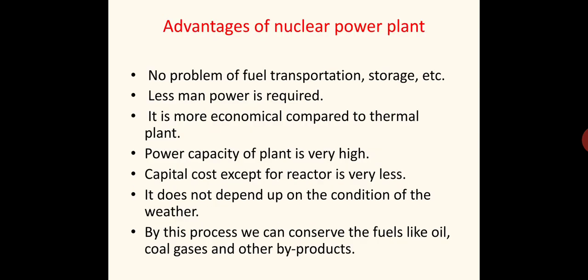Now coming to the advantages of a nuclear power plant. There is no problem of fuel transportation, storage, etc. That is the main advantage. Less manpower is required. It is more economical, with less manpower. Of course, very much technical knowledge is required for the person operating this. It is more economical compared to a thermal plant. The power capacity of the plant is very high. The capacity cost except for the reactor is very low. The cost of the reactor is actually very high, but the total cost is less. It does not depend on the condition of the weather. Whatever the weather, it will work. By this process, we can conserve fuels like oil, coal, gas, and other byproducts. This is the main advantage.